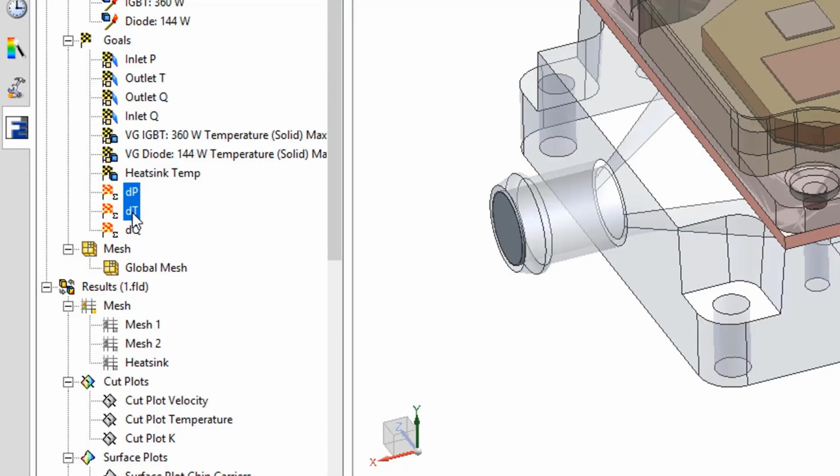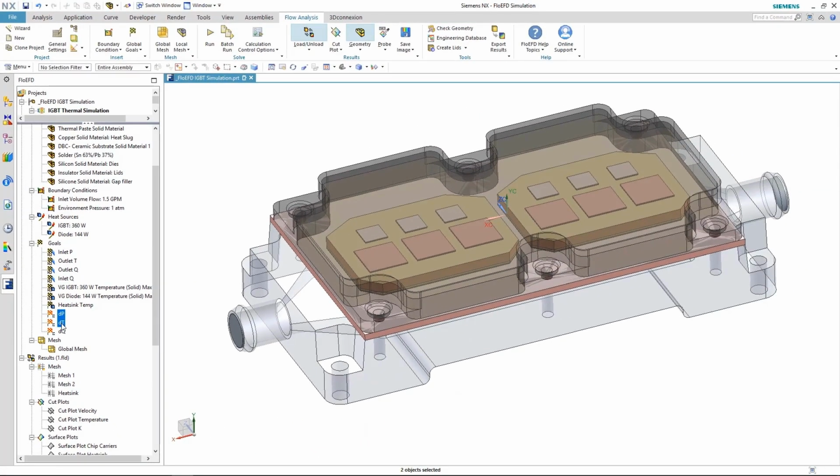During the actual solver execution, the usual Navier-Stokes equations are being solved to ensure conservation of mass, momentum and energy, but the solver is also checking the goals to ensure steady-state convergence behavior before the solver will stop. The convergence criteria can be adjusted for user-defined accuracy.